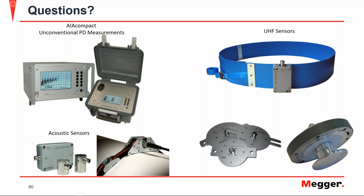So while the IEC 60270 measurement gives me values in picocoulomb, as Charles has explained in his webinar, in picocoulomb we can't measure when we are applying the UHF method. So if we are measuring in the UHF method, we are measuring a voltage, and accordingly there's a slight difference in the value of the amplitudes that is displayed in my PRPDs, but otherwise they are comparable, yes.